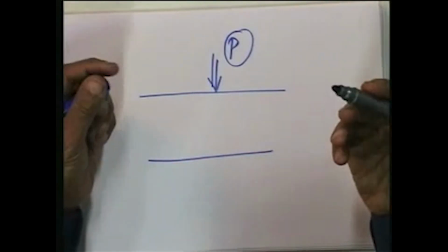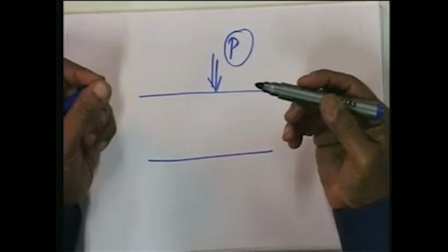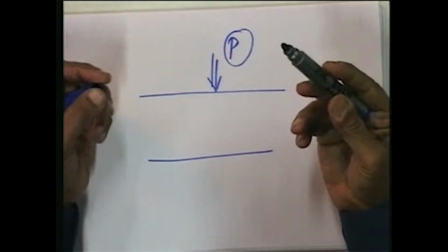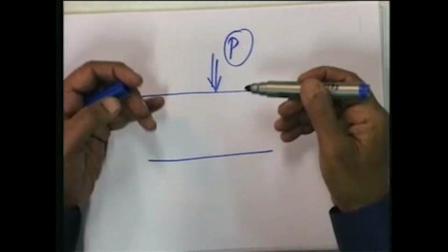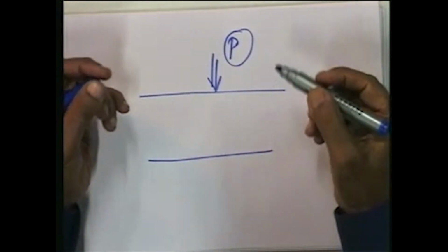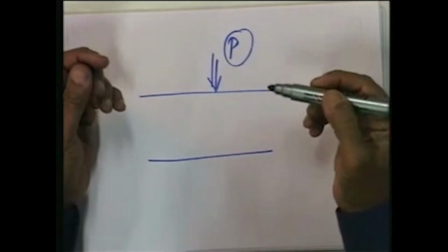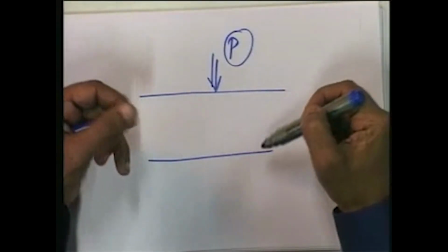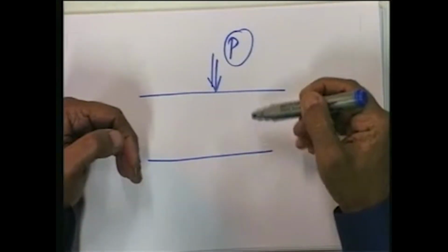So, we remember our discussion with respect to pre-consolidation and over consolidation. This is precisely that. We are in fact taking advantage of the knowledge of that phenomenon. We are consolidating the soil beforehand and then applying the load, so that any further consolidation, if it takes place, will be minimal and will be normal consolidation.